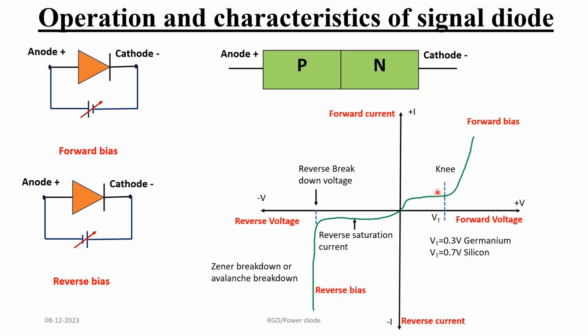So when the level of voltage applied is across the barrier voltage, then the diode PN junction will allow the current to flow through it. The relationship between the voltage and current is nonlinear, or we can call it exponential, which we could see in this forward biased condition. In the forward biased region, the flow of current increases rapidly when the voltage increases a little.